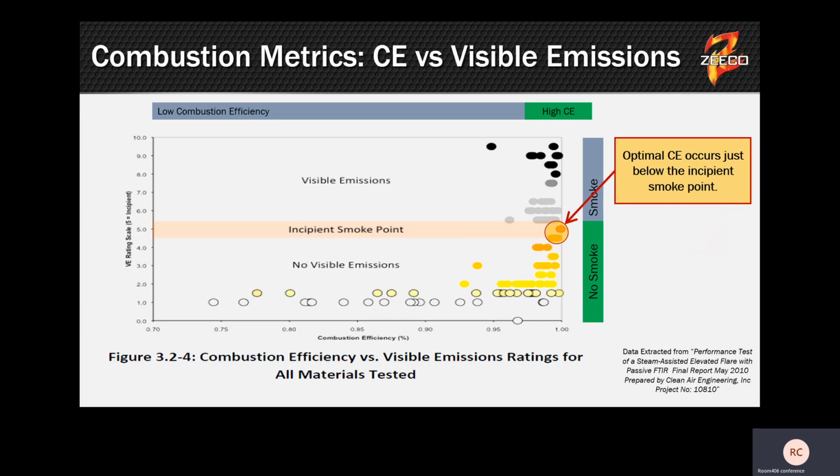And what it's doing is taking two infrared inputs. One really understands the carbon in combustion, and the other is looking generally at the oxygen in the combustion zone. It makes a ratio. So that ratio, independent again of what the flow rate is, independent of what the composition is, needs to generally be the same. And so if you control to that right ratio, you're going to have generally good flame quality.